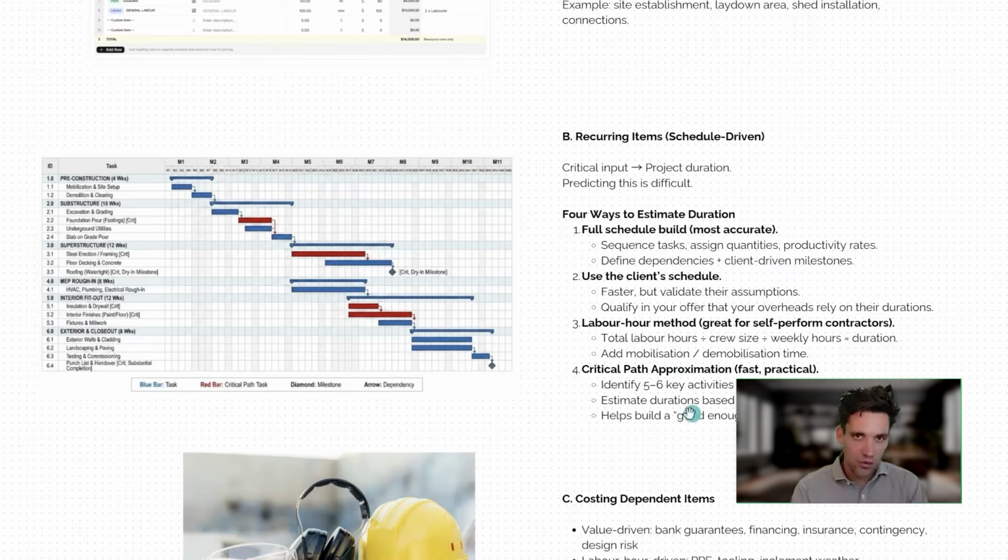The only important risk to be aware of if you're going to do this is you need to look at the actual durations of the tasks, the quantities, your key production rates for the items where they are specifying the duration. Because if you were saying you're relying on their schedule, it implies that you're committing to the duration they've given you to do your work.